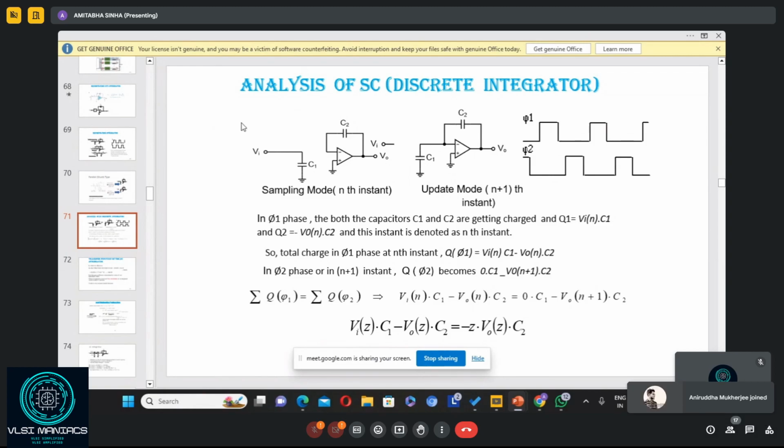Then we need an inductor and a capacitor, and we put the values accordingly. And if we want to implement it by a discrete circuit, we need adder, subtractor or multiplier and delay units, and accordingly we put them and make the circuit. So that is the way of designing any circuit, be it analog or digital.